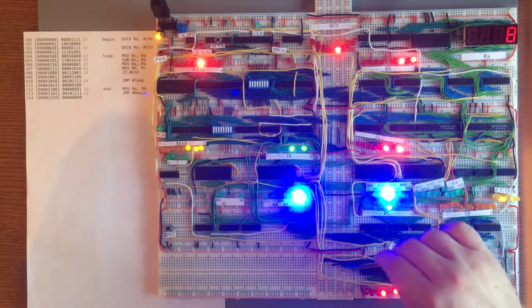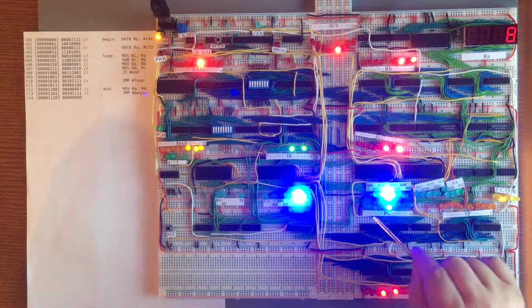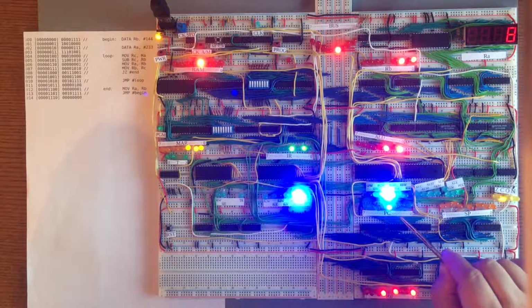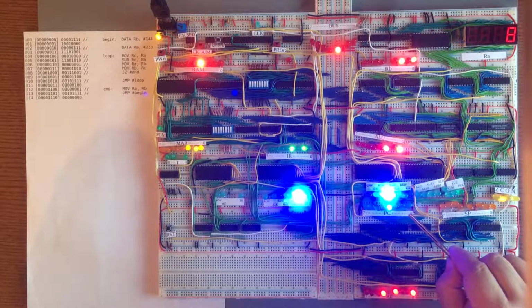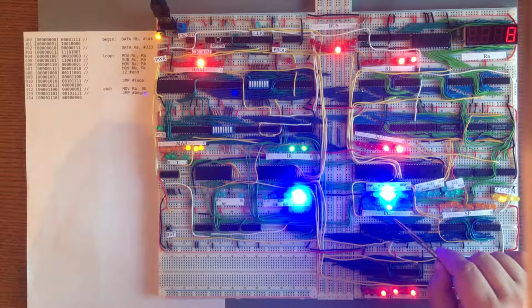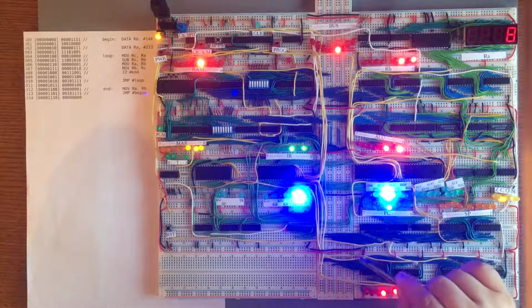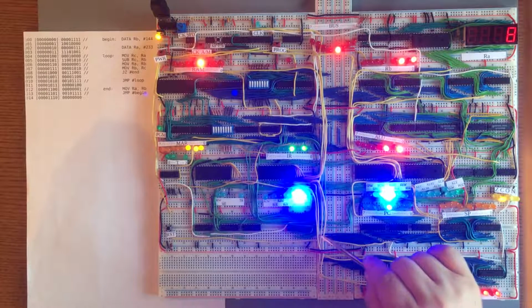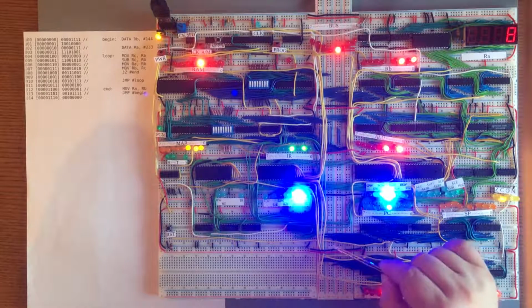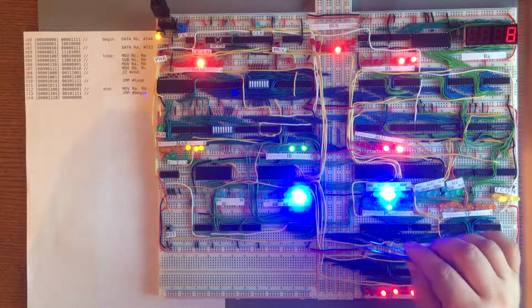In this design, for example, our program counter is 8 bits long, and that's a difference from Ben's design, because on Ben's computer his program counter is only 4 bits long. And that means that on Ben's computer, when his program counter is enabling its value onto the bus, it's actually only enabling 4 bits, and his 4 higher bits are not set at all. They're not 0 and they're not 1. They're not connected to anything.